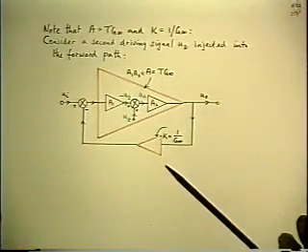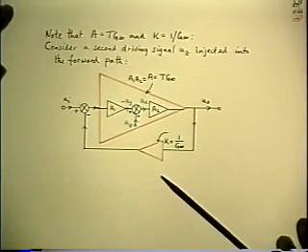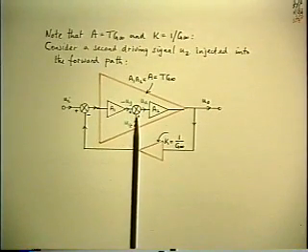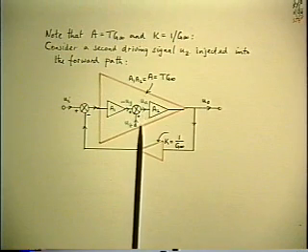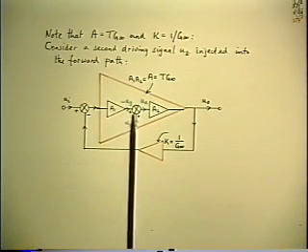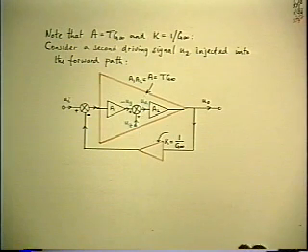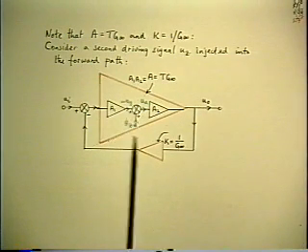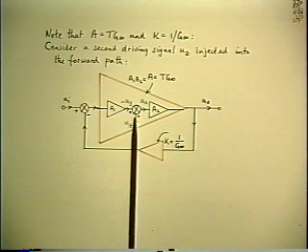The loop gain is going to be determined by injection of a test signal into the forward path. I've generalized the signal now to a UZ, and it's represented in the ideal block diagram simply by a summing junction. It's a phasor summing junction, of course, but that's all it's doing.